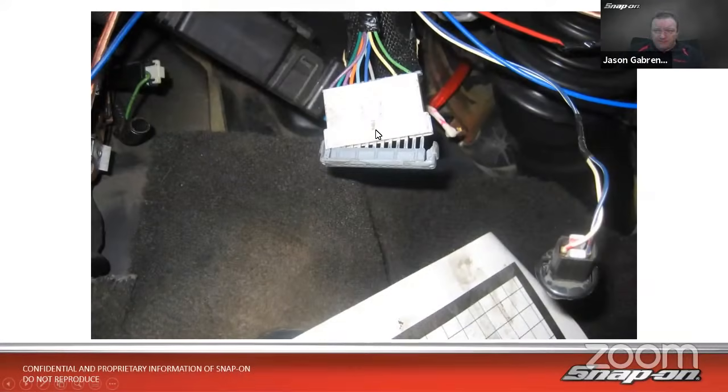It's 12 pins. Now, what we could do is use jumper wires. If you've worked through the flow chart on one of these cars, it says use jumper wires or paper clips, that sort of thing, to check for communication between the modules. So you put one wire where the DLC comes in, and then you go to the ECM, then to the TCM, et cetera, and see how the network performs.